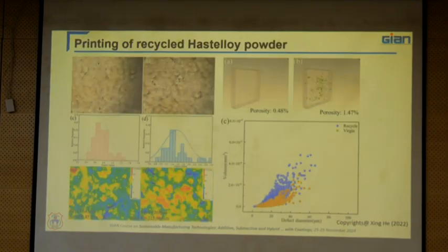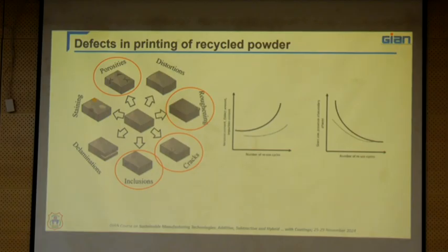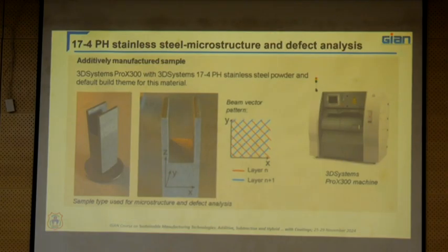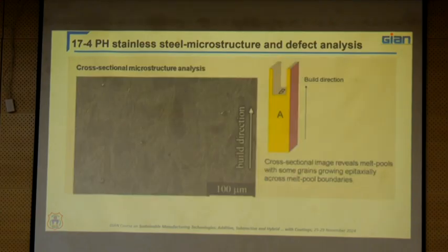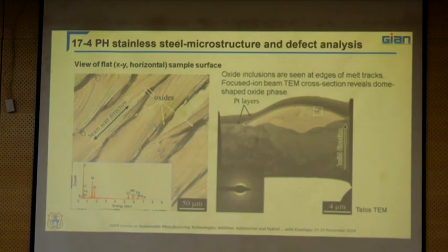As I told you, the properties are going to be affected by porosity, distortion, straining and delaminations. If you see here, what happened is that with both the original and the reused powder, the part got deformed. The part got deformed because of the reused powder, which creates deformation in the printed part because more straining takes place during printing. We are supplying more energy, either because of oxidation or to melt and minimize the porosity levels, and because of that it creates deformation in the parts.